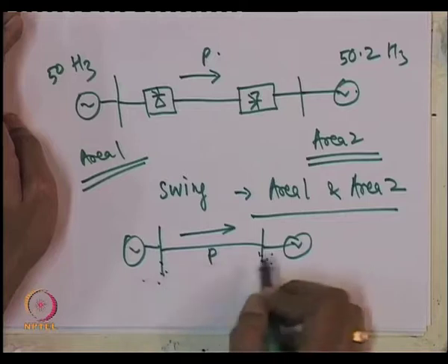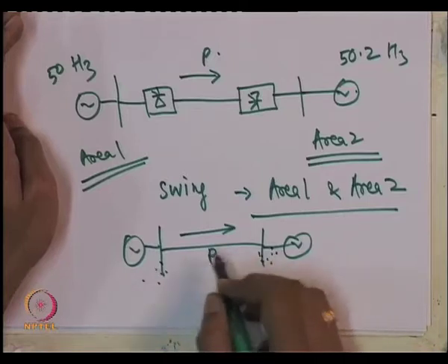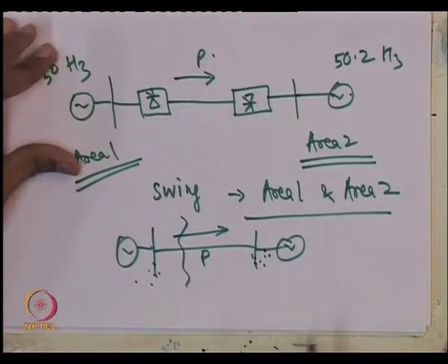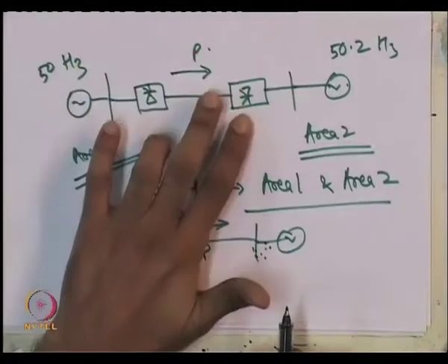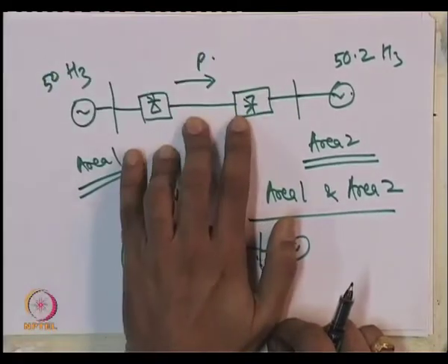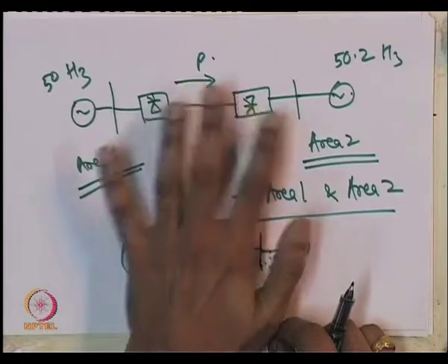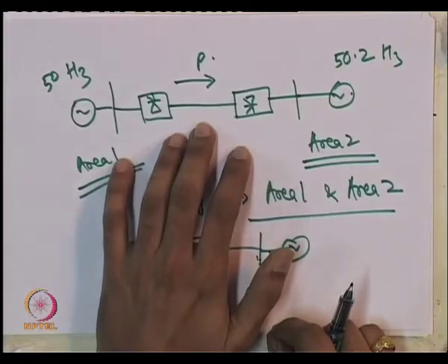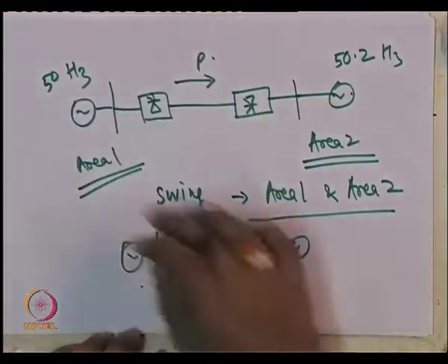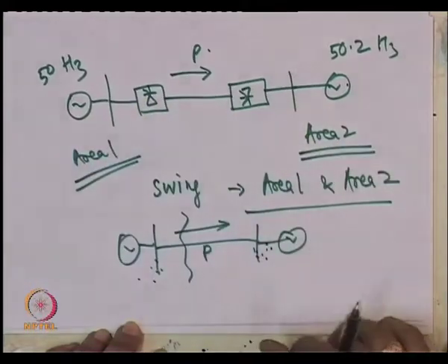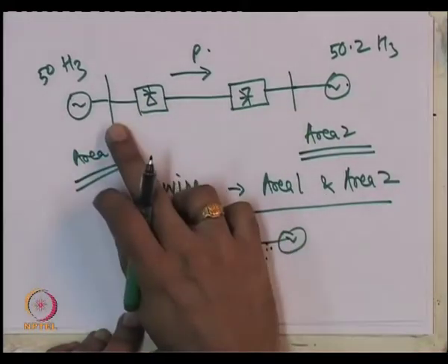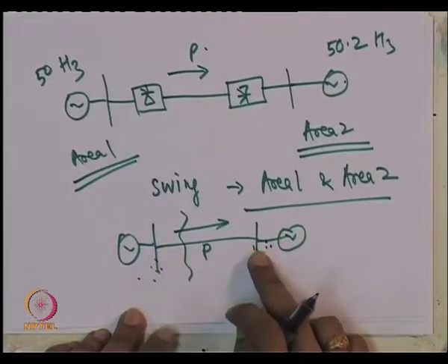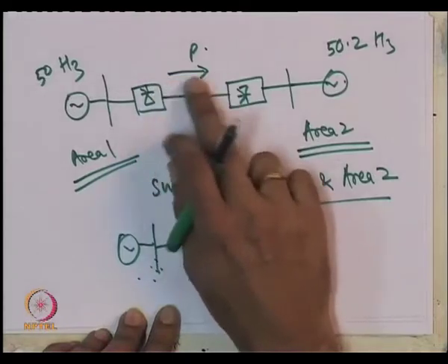Okay. And if the two machines lose synchronism due to large disturbances, you can't operate and you will have to separate out the system. This is not a problem in an asynchronous link. Okay. So, power system stabilizers are not applicable in this scenario. There is no problem if these two areas are operating absolutely at distinct frequencies, and the swings which you see when you have got an AC interconnection are not seen here, because power flow is absolutely regulated.